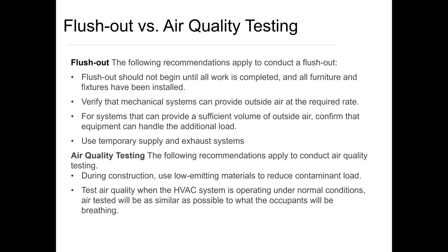You want to make sure that the mechanical systems can provide the appropriate amount of outside air. And for any systems that can provide a sufficient volume of outside air, you want to make sure that the equipment can handle that additional load. And then using any type of temporary supply and exhaust system.